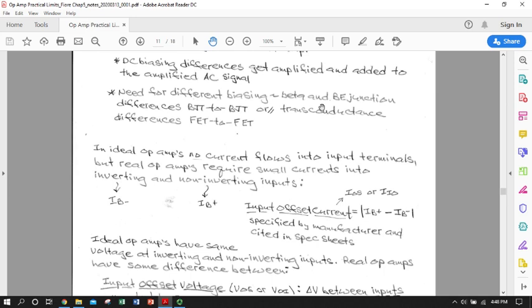So here we're going to walk through how some of the things that we measured in that first lab are actually listed in the datasheet, so we can use them as design inputs without having to use an ammeter or measure current with a calibrated resistor with our scope, and get an idea of how we would design around what we know is not going to be an ideality in the circuit.